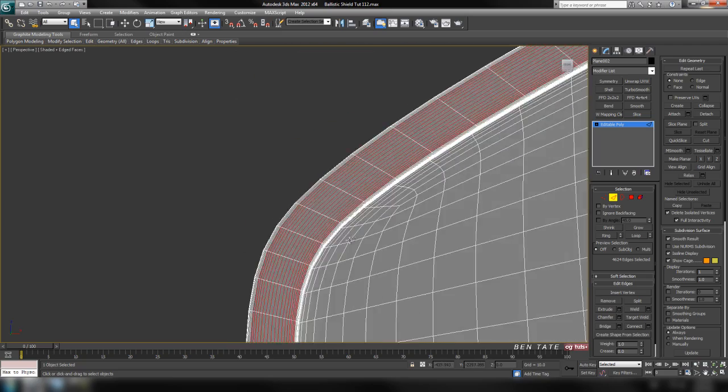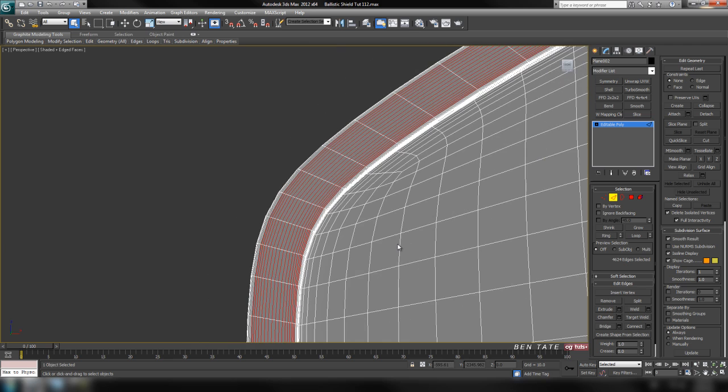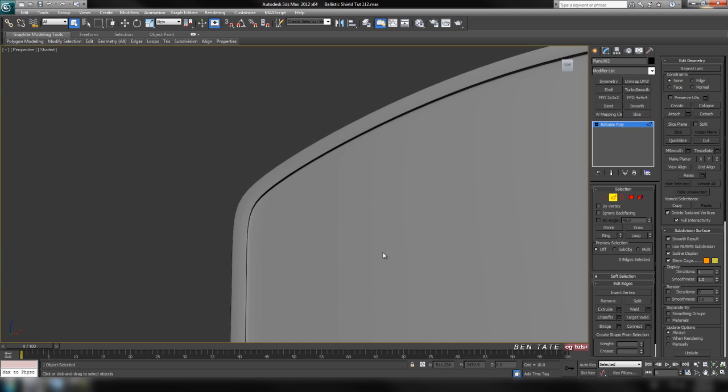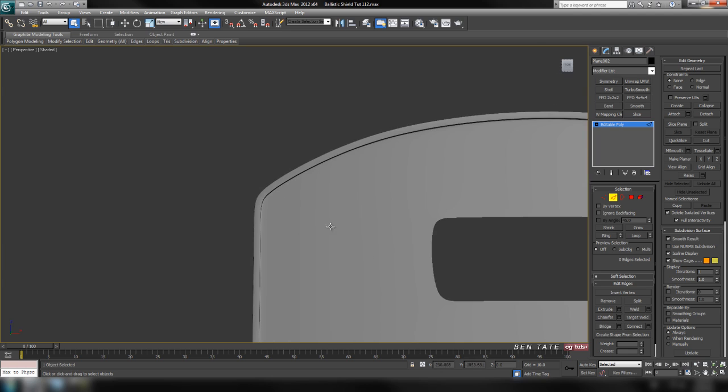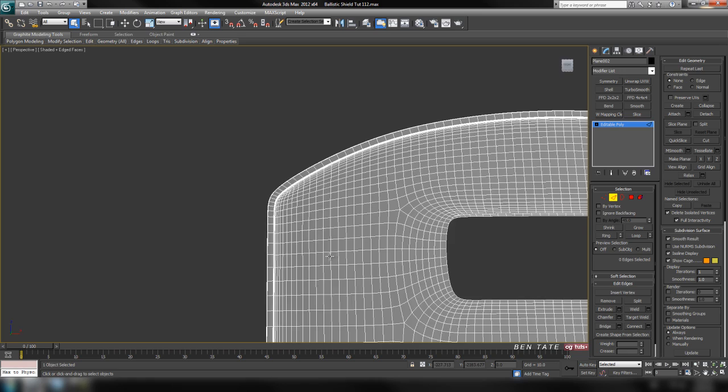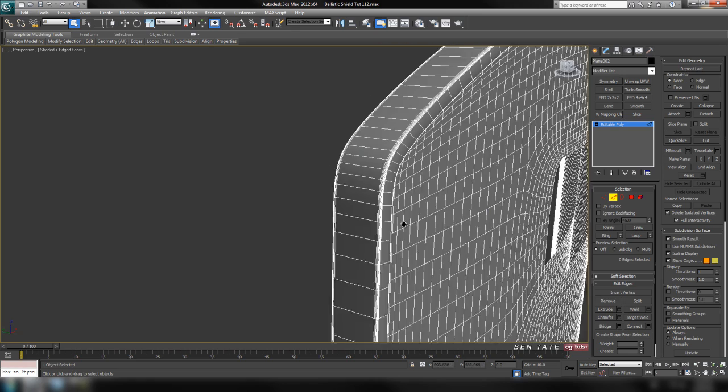And you can see we have another 4600 edges selected that we don't need, so we'll just hit Control Backspace and just once in a while check to make sure that it actually looks okay after the edges are removed without your wire on, and you can turn that on and off with F4. Okay, so we'll do the same thing on the back.